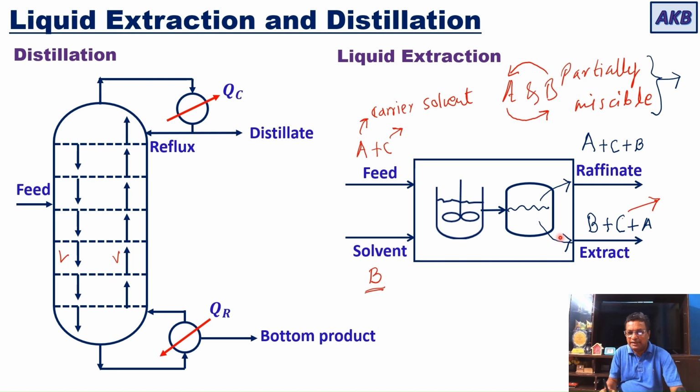So are you understanding it? In liquid extraction, you have the cost of solvent that is involved. You are adding solvent from the outside. And then after extraction, in order to recover the solute from the extract phase, we will have to use distillation.